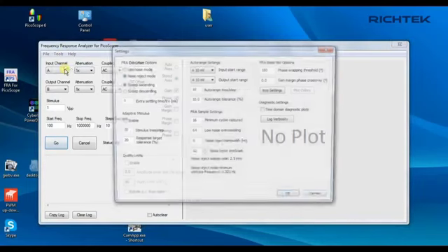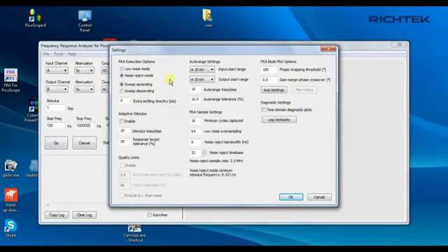In the Tools Settings menu, you can choose the more advanced settings. I will mention the most important ones. For gain phase measurements in switch mode power supplies, you should always choose the noise reject mode. Minimum cycles captured can be kept around 16, but keep in mind that a 1 Hz stimulus measurement would take at least 16 seconds. Lower noise reject bandwidth will improve the signal-noise ratio but requires more samples. A good value is the minimum measurement frequency divided by the number of captured cycles.